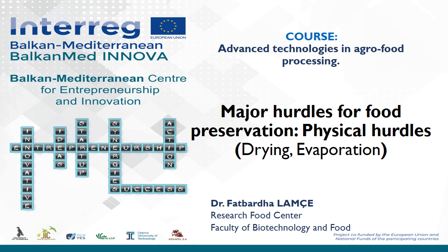Drying is one of the oldest preservation processes that is usually performed on solid materials. In most cases, the drying process involves the removal of a small amount of water from the solids at temperature below its boiling point. And evaporation is another kind, because it is usually used to remove a large amount of water from solutions, and this removal occurs due to the boiling of the solution.